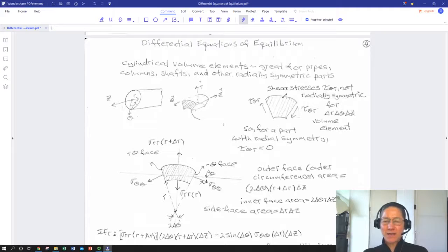So we have a radially symmetric body where all of our stresses, basically the r theta stresses, are going to all cancel out effectively when we start summing them all the way around. But we have opposite directions with nothing to balance when we go all the way around in the case of our taus.